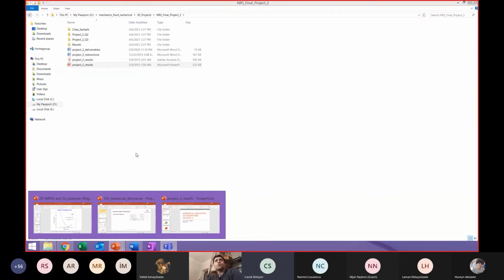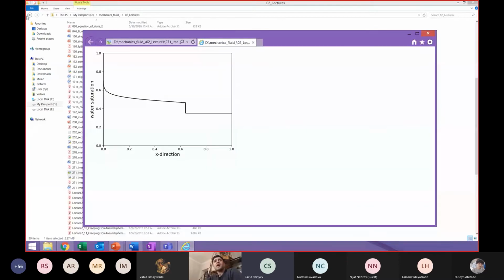So this is the solution basically, and from the left side, we're injecting water to the reservoir, which is saturated initially with both water and oil. The water can be at the irreducible level, or we may have some initial water saturation which is higher than the irreducible water saturation. And on the right hand side, we're basically producing.